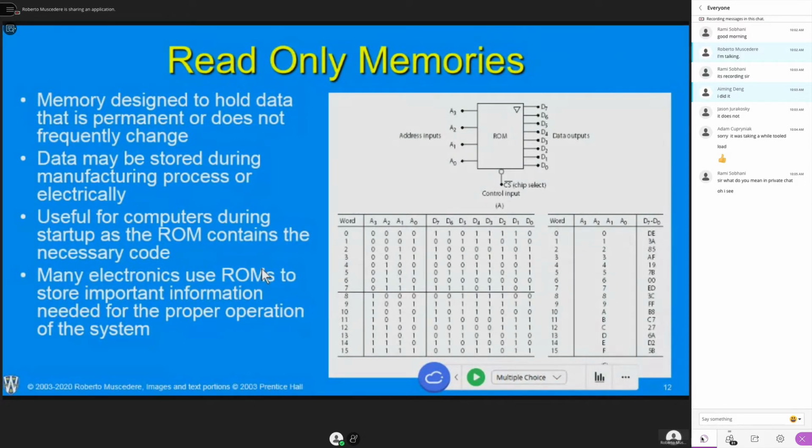Okay, so the other day I was talking about read-only memories, and these are effectively memory devices that are not only read-only, they're just harder to write to, we'll say. They don't write within the same amount of time we could read from them, is really their definition. I gave an example of a pretty simple ROM type device where we have 16 words. We can see A3 to A0 as our inputs. It has an 8-bit output, D7 to D0, and that's what our circuit would want to see, ones and zeros, because we're always using switches that respond to that.